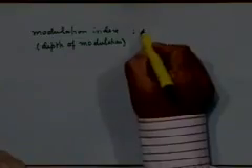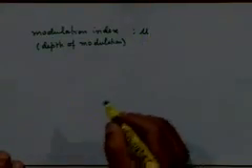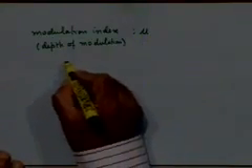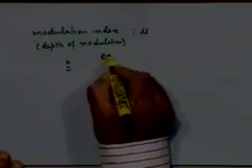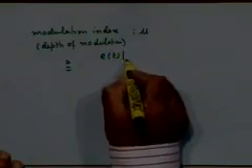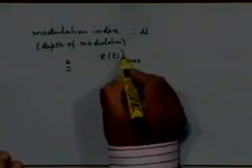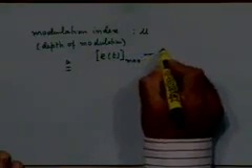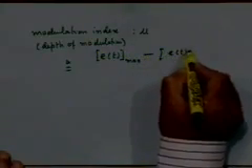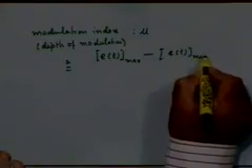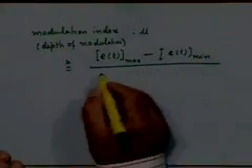Basically, it is the relative variation of the envelope from maximum to minimum values, and that's precisely the way it is defined. We will denote this parameter by mu, and it will be defined as follows: the maximum value of the envelope minus the minimum value of the envelope, divided by the sum of the two.